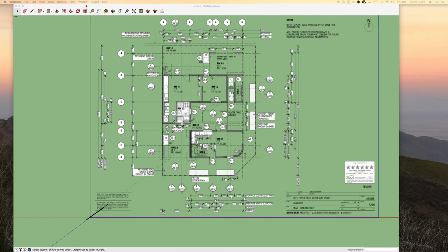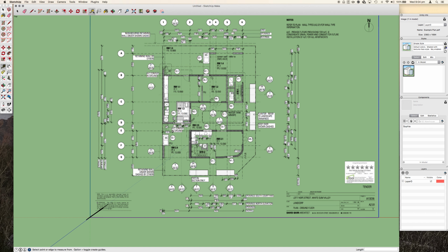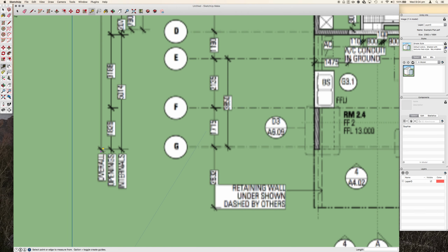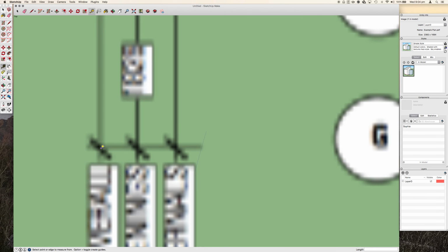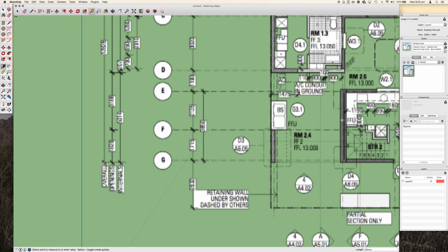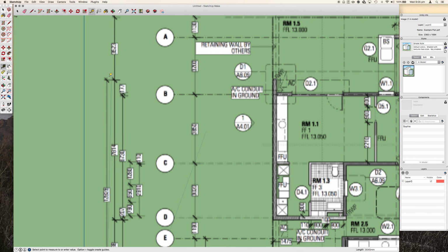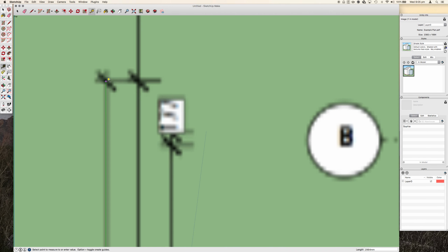And there's a couple of ways of scaling it. If you want to scale the whole model, you can just select this little tape measure here, and then just measure out that dimension. At the moment it's only 3 meters. It's meant to be 12828 millimeters. And it asks you, do you want to resize the model? That'll resize everything.